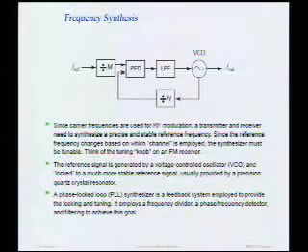Now, most of you have used a frequency synthesizer. If you've been in the lab and you've done an experiment, and the experiment was set the input to 10 kilohertz with an amplitude of 1 volt, well, inside that little machine there's a frequency synthesizer that generated that tone for you. In a wireless communication system, we often use a frequency synthesizer to generate that LO, that local oscillator, which is used in the mixer, let's say for frequency translation.